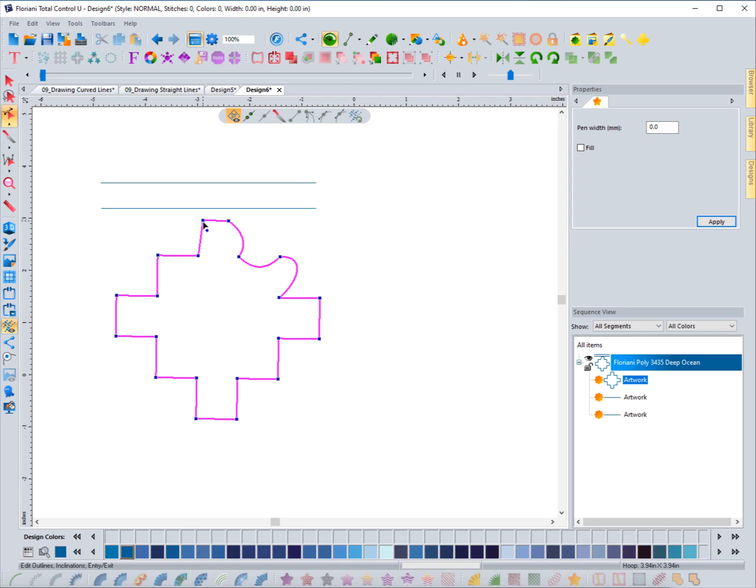So it's just important to understand what that is and how that works. So we've learned how we can click and drag the points, and we can drag the lines and make them more curved into a different shape, and we can move it all around. I'm just clicking and holding and get it to where I want it. And by adding a curve to a line, now when I click a node that's attached to it, I'm going to get the handlebars. If I don't have a curve, straight line, I don't get those little handlebars.